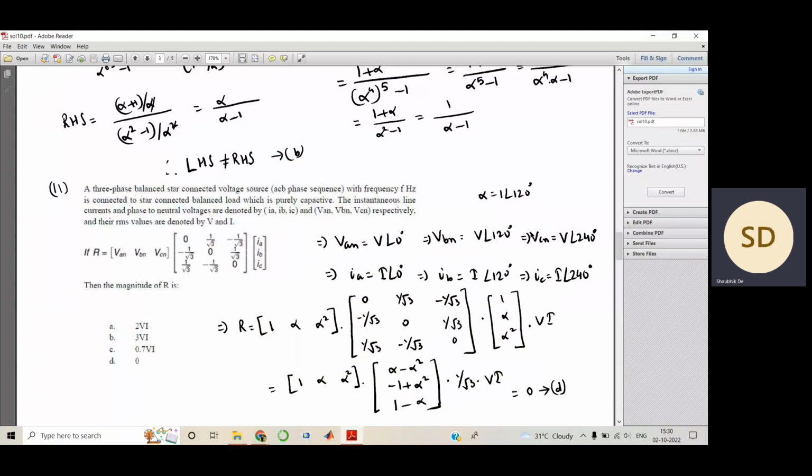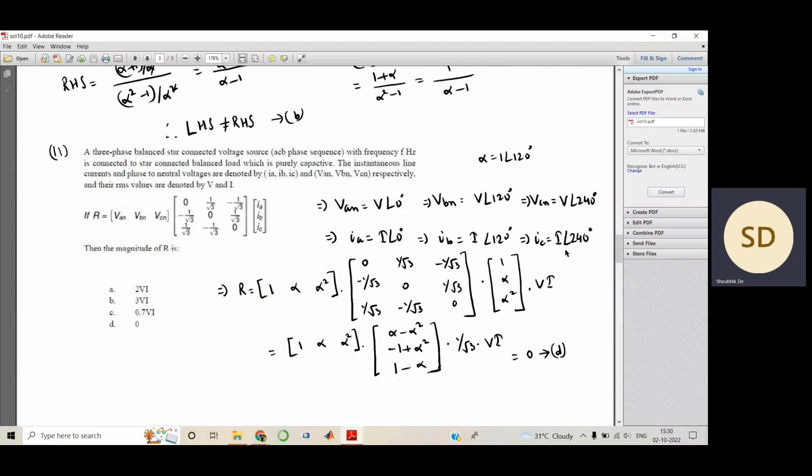And in this way we write these kind of expressions, right? You have solved this previously. So for three phase, phase B would be at an angle of 120 and phase C would be at an angle of 240, right? Here I am replacing the one at an angle of 120 by alpha, so this would be alpha square, right? You just replace these components in these expressions and you get whole of this, right?